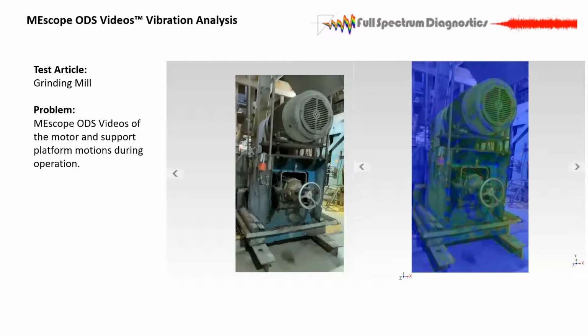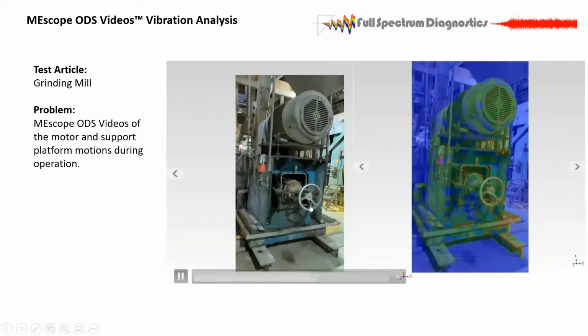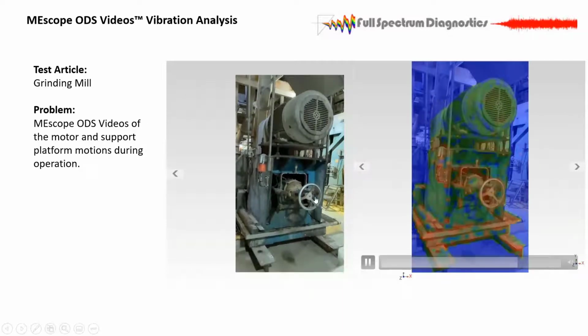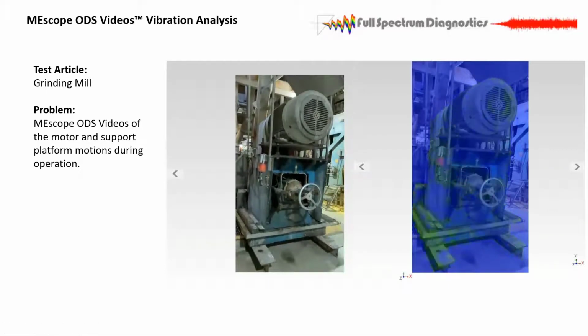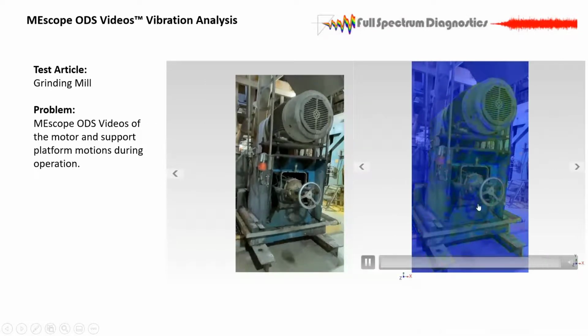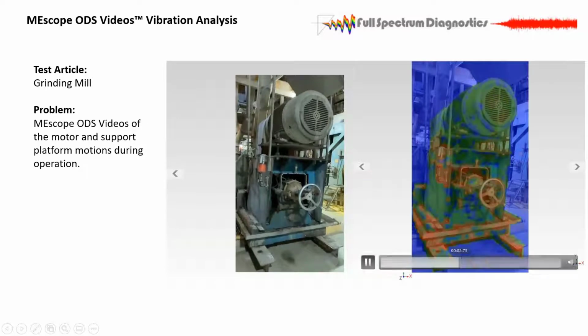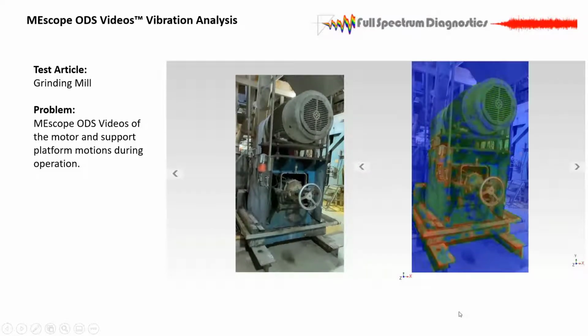This is another grinding machine. So this is a secondary grinding. So all that corn powder comes down and goes through this, and they have a bunch of different grades. So they can change the engagement with this wheel, which throws everything off. So there's an alignment feature. You know, they try to hit a sweet spot in the middle where they have a little leeway between processes of different fine grinds that they need. As a result, you know, they introduce unbalance and misalignment and all kinds of things in the whole structure. So what you're seeing is one of those modes, one of those bouncing modes of the whole structure.